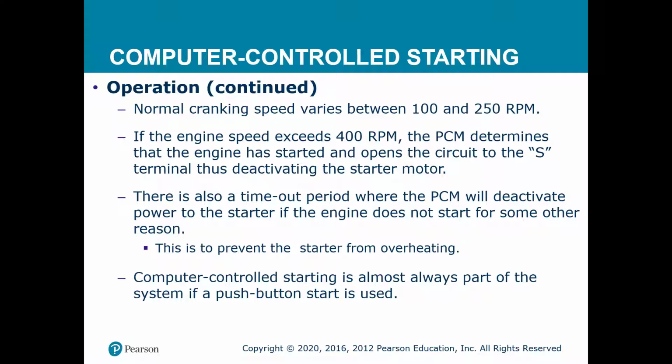Now, there's also a timeout period where the PCM will deactivate power to the starter if the engine doesn't start or for some other reason. This is to prevent the starter from overheating. Now, this can throw people off, or it started to back in the day, when you would go to start your vehicle and let's say it didn't have gas in the tank, or you had a bigger problem like an ignition system issue or a fuel system issue. You would turn the key, the vehicle would attempt to start, and then you'd let go of the key, but the vehicle would continue to keep cranking. We called that ghost cranking. And it's very common now. You're probably familiar with it. It'll run for a predetermined amount of time and then shut off.